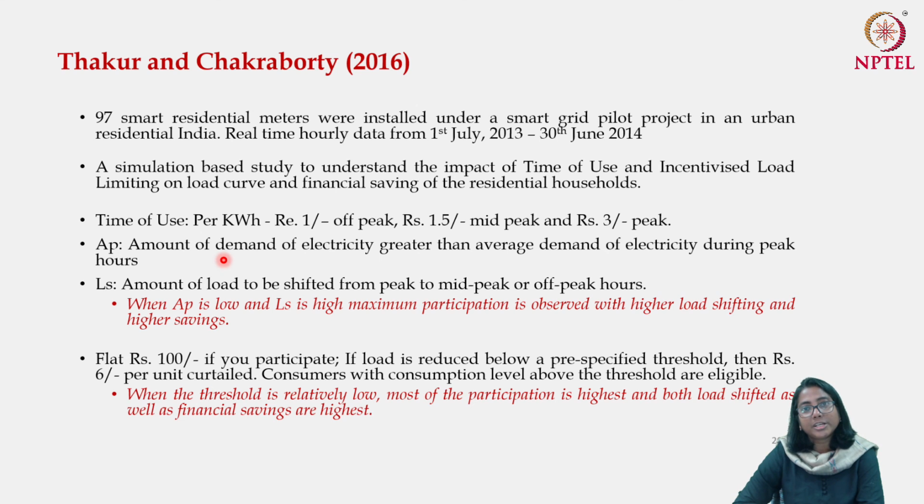Now, one interesting observation if you go through this paper is that you have to really intelligently choose AP and LS. Because if you are setting up your incentive in a not right manner, and there happens to be a lot of load shifting, then instead of flattening the load curve, you may end up having a new peak during the off peak period. That is also possible. So this kind of simulation actually gives you an idea what should be the optimum tariff structure, what should be the optimum load that you want to transfer, what should be the optimum gain.